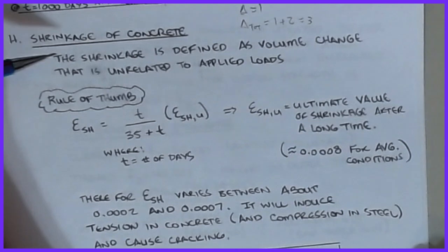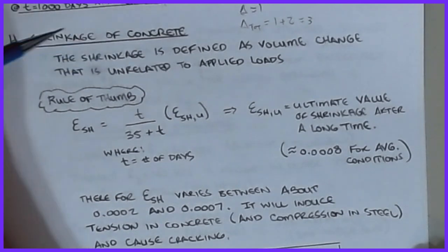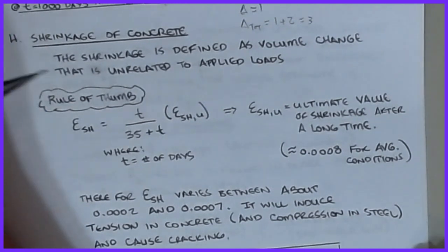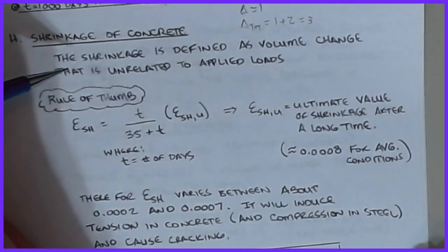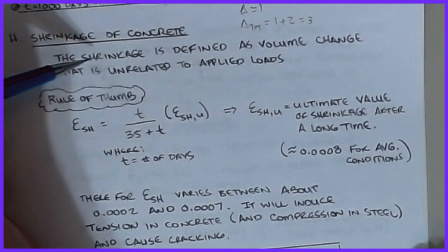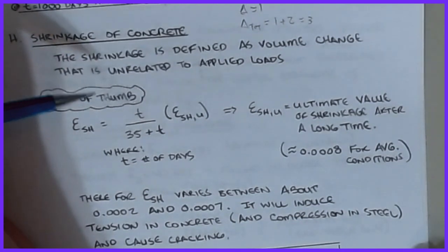If they pour a sidewalk and don't cure it correctly, you can get micro cracking in the top surface of a slab, just because the concrete at the top behaves differently than what's down inside of that particular slab, by the nature of the curing process. And so shrinkage is something we're trying to provide for. This will generally dictate some amount of minimum steel in a slab